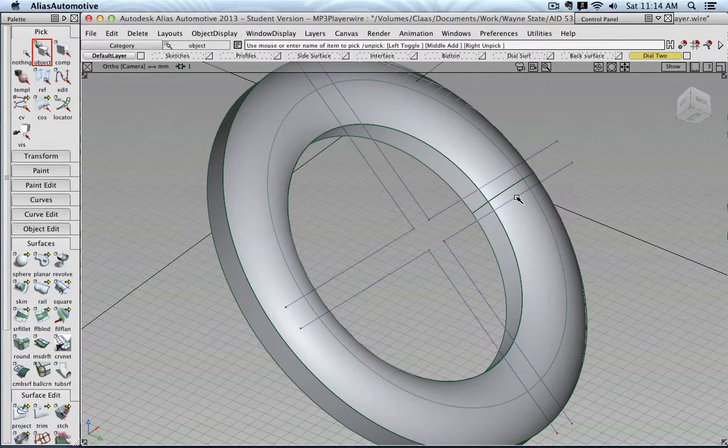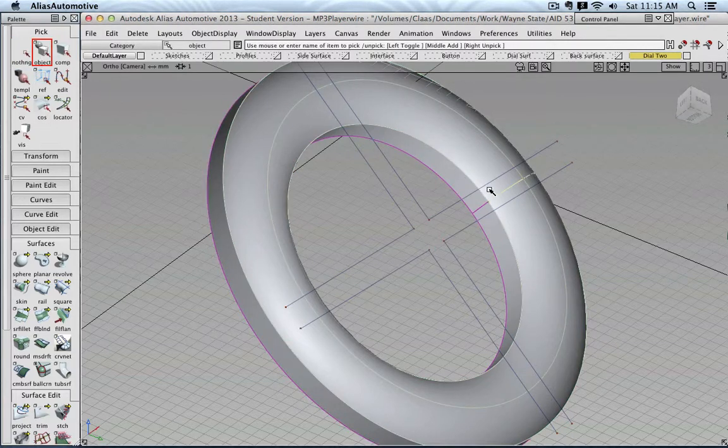In this case, it's actually smarter to create those extrusion surfaces by sampling from the Revolve surface, because we will share this edge among all 3 objects instead of using the rings I created to create new surfaces from there. In addition, this is also in relationship to each other. You can see that the extrusion surfaces are driven through the construction history with the surface draft tool from the Revolve surface.